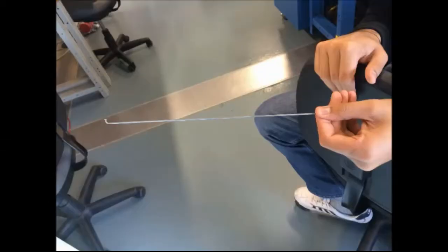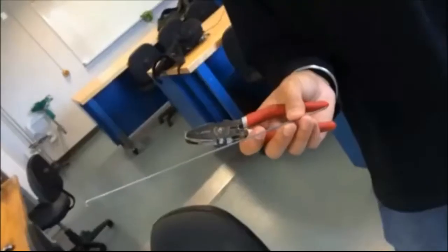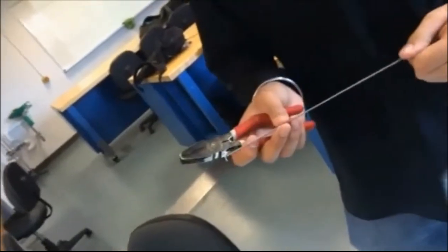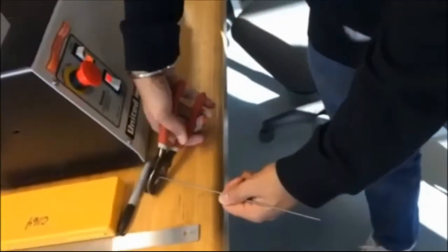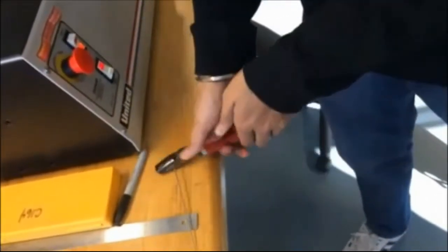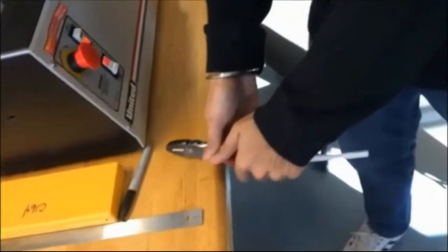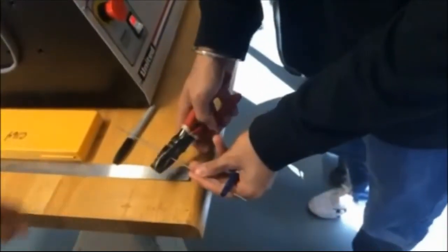9913494415. I'm going to tell about the procedure. We took a cycle spoke which is already cold worked and cut it into two halves. The head of the spoke was also removed with the help of the pliers. One part is put on the UTS tester and the other part was put in the furnace, which is already set at 950 degrees centigrade. The other part was kept in the furnace for about 30 minutes.